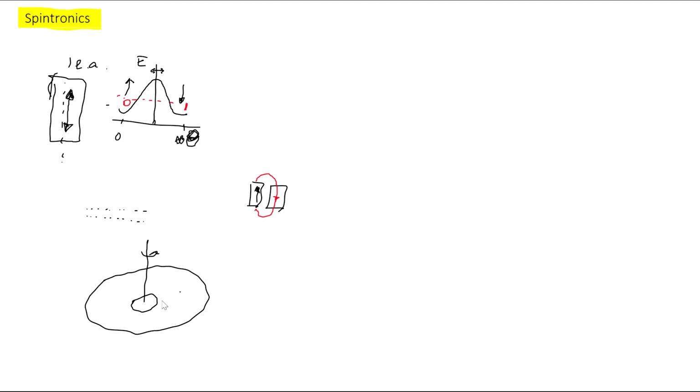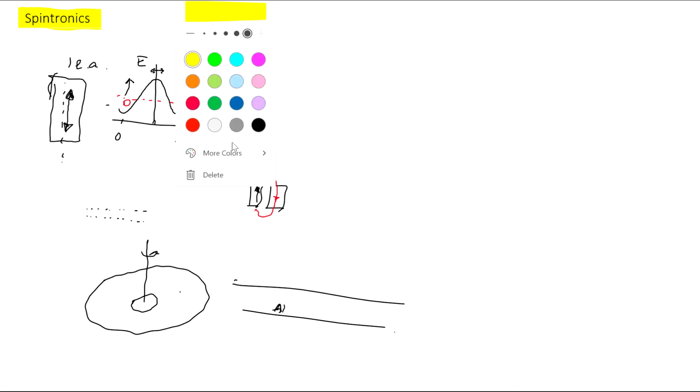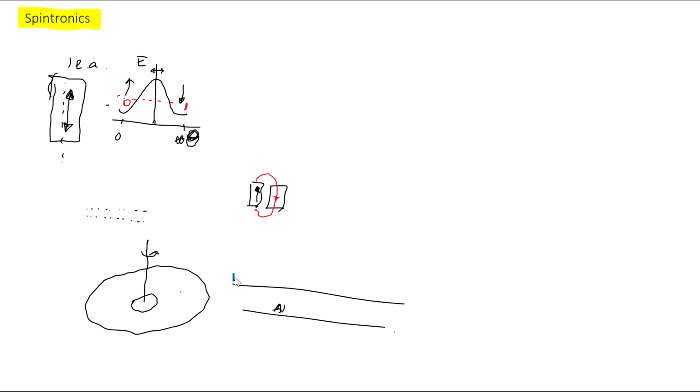If you take a cross section of this disk and look at this disk area, the disk is typically made of aluminum, it is light and easily machinable, and on top of that disk, let me use a different color, some dark color with a small size, on top of that disk we deposit a magnetic film, and that magnetic film can be magnetized either up, oh that's not a very good color, but either up or down.